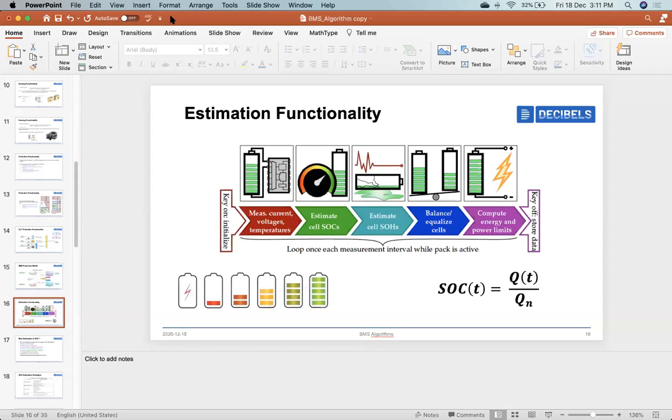If you see the scooter market, 48 or 72 volts is more than sufficient if you're building a simple scooter without high performance, so your system is not a challenge in terms of safety. But definitely if you go for higher performing systems, you will have to go for higher voltages.